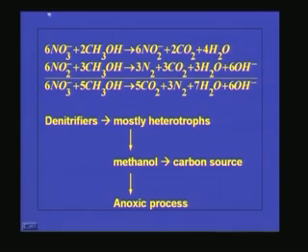And in this denitrification, we have discussed that for any metabolic process the energy is derived from oxidation reduction reactions. For any oxidation reduction reaction, there should be an electron acceptor and an electron donor. Here the electron donor is nothing but methanol. Methanol is acting as the electron donor, and we want to reduce this NO3 to N2. So this is getting reduced. When one compound is getting reduced, it will definitely be accepting electrons. So in denitrification the electron acceptor is nitrate.